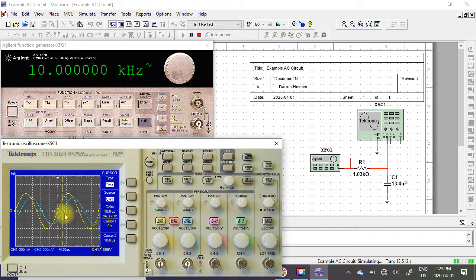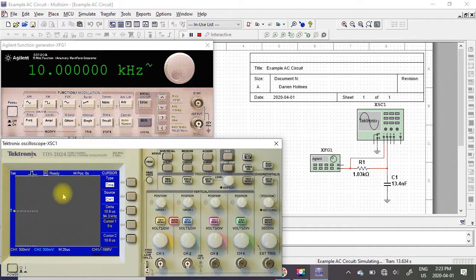So that calculation works out to 38 degrees. So when you take a look at your waveform, we know the peak happens at 90 degrees, so halfway between the zero crossing and the peak should be about 45 degrees, so this happens a little bit before the halfway point, so 38 degrees looks like it's about correct.